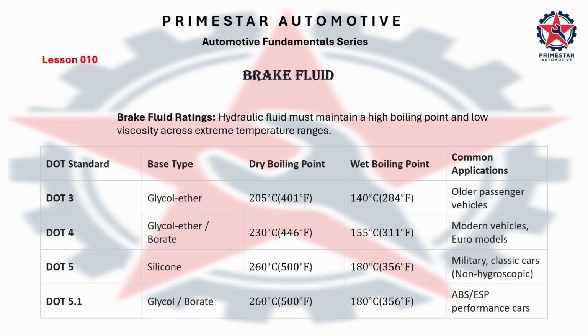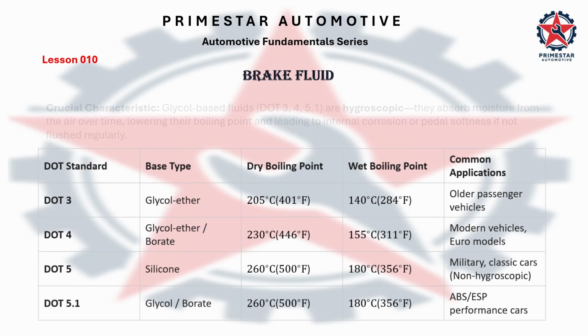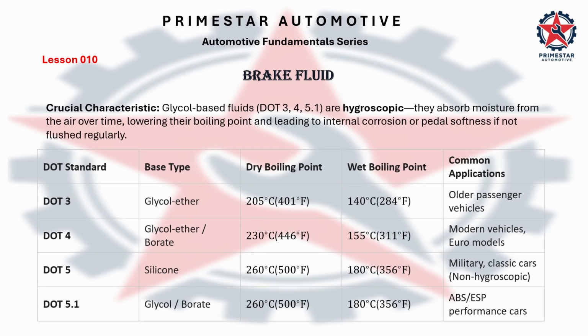Brake fluid ratings. Hydraulic fluid must maintain a high boiling point and low viscosity across extreme temperature ranges. Crucial characteristics of brake fluid: glycol-based brake fluids DOT 3, 4, and 5.1 are hygroscopic. They absorb moisture from the air over time, lowering their boiling point and leading to internal corrosion or pedal softness if not flushed regularly.